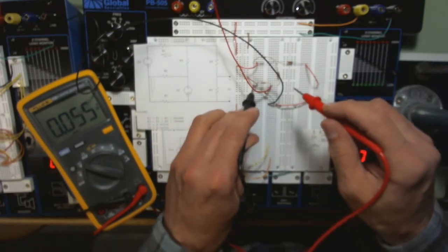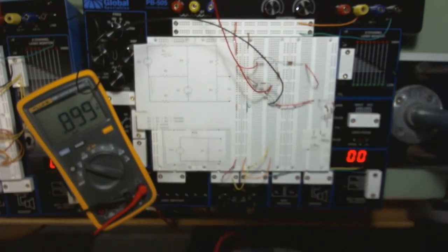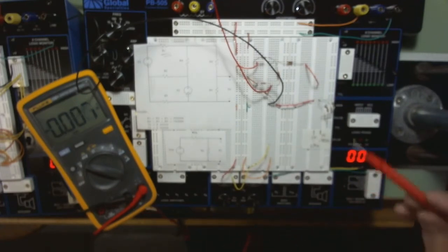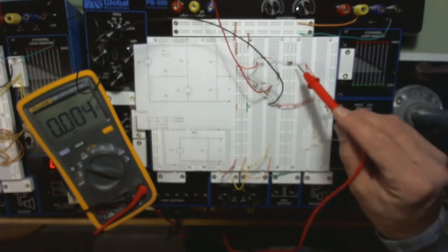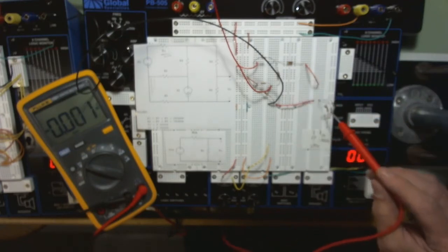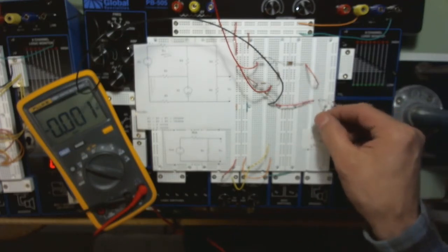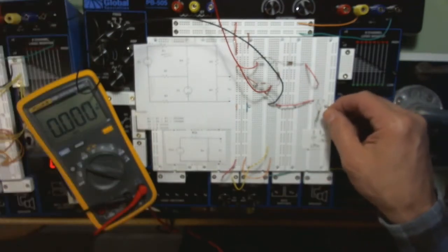And that this should have been pretty close to 9. Yep. Good. Okay. So we've measured the open circuit voltage across here. With this open, we showed that the voltage across there was 0, so the current through there is 0. And then we had a 2K resistor across here and a 1K resistor across here.